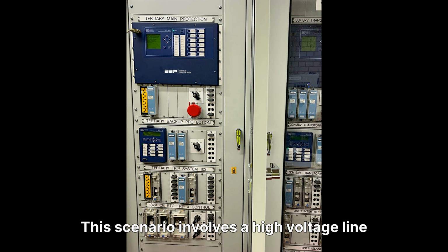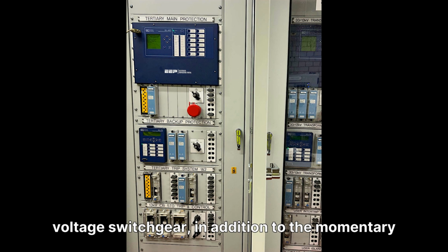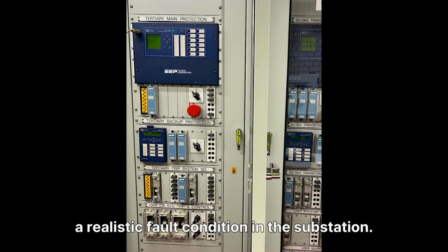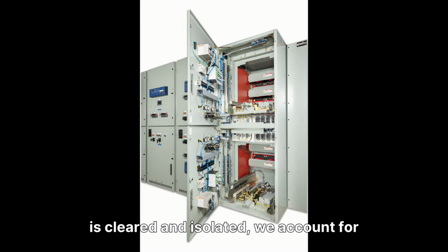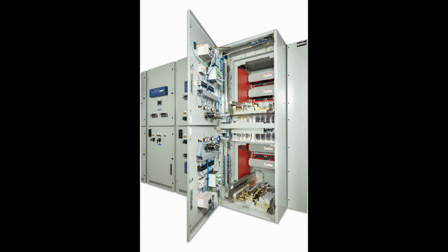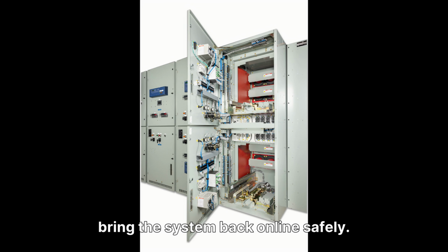This scenario involves a high-voltage line feeder trip, accompanied by a transformer feeder trip and the tripping of all medium-voltage switchgear, in addition to the momentary loads from control and protection panels, simulating a realistic fault condition in the substation. At the restoration time, once the fault is cleared and isolated, we account for the closing of one high-voltage breaker along with the simultaneous closing of an incomer and an outgoing feeder from the medium-voltage switchgear, representing the steps to bring the system back online safely.